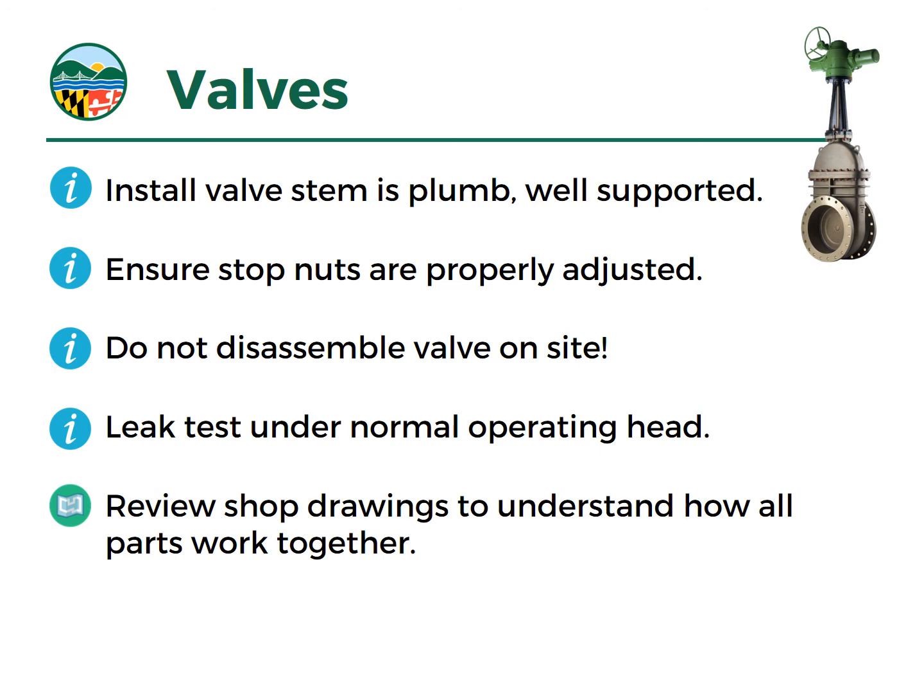So when you install a valve, you want to make sure the stem is plumb and well supported, so that you don't want that long stem to kind of act like a string of spaghetti.